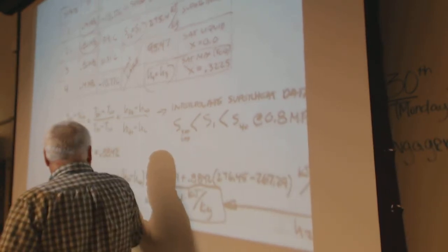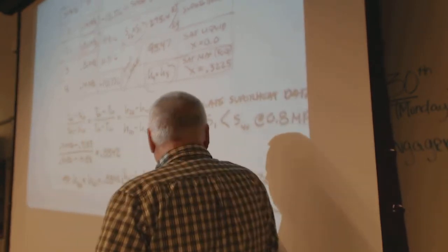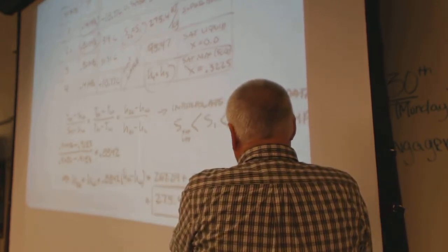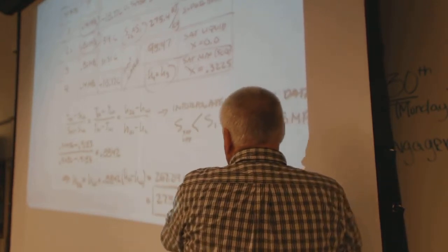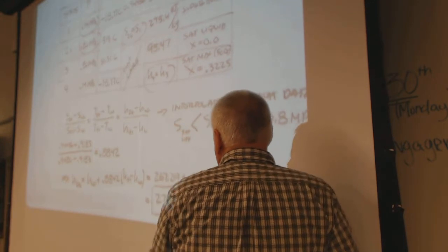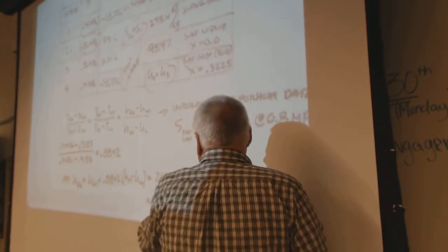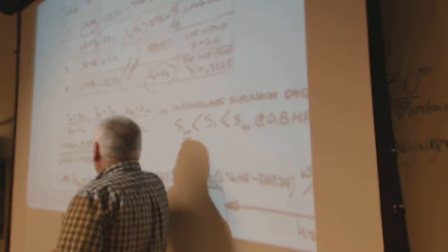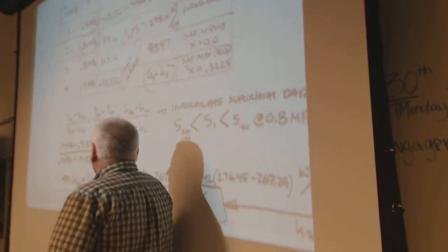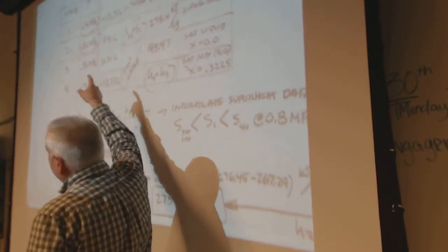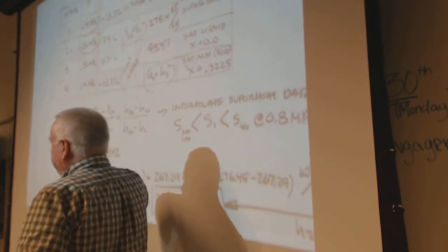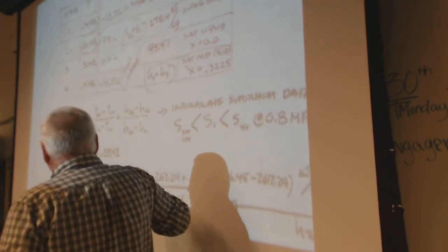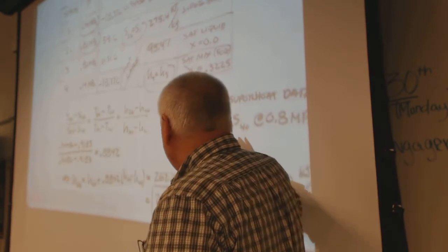So we do that for the H values. Between 30 and 40 degrees, 88% of the way, plus the value for 30, you get this value for H. And because it's between 30 and 40, that's 9/10 of the way, so I call it 39 degrees C. If you look on the tables, you'll see where these are coming from.